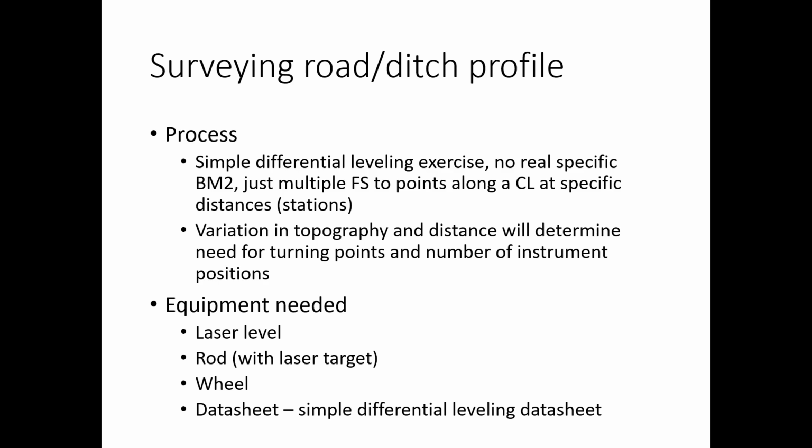Okay, so the first one we're going to talk about is surveying a road or a ditch profile. Again, it's just a simple differential leveling exercise. However, there's no specific benchmark that we're looking for. We just shoot multiple foresights to points along the center line at specific distances, which we'll call stations.